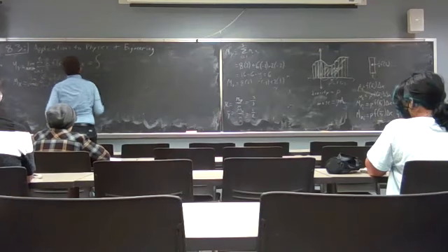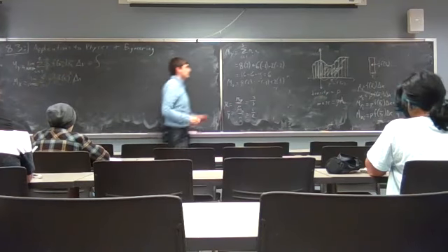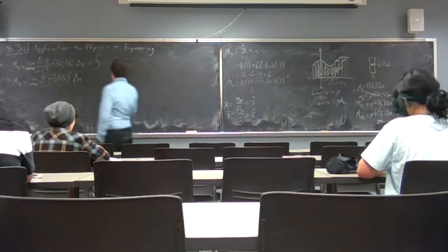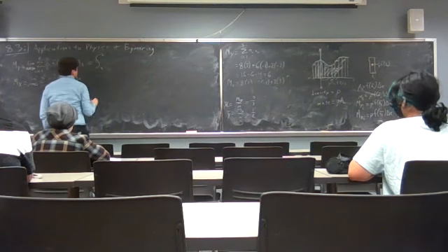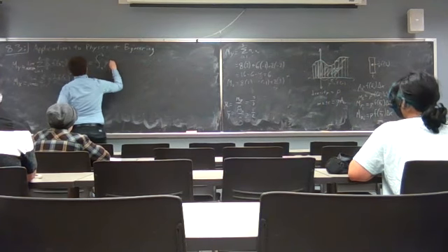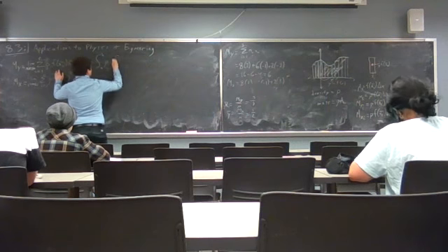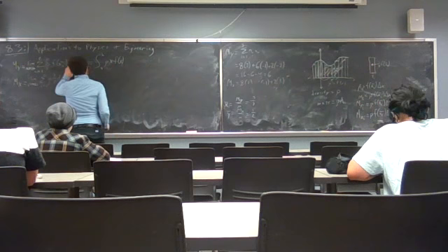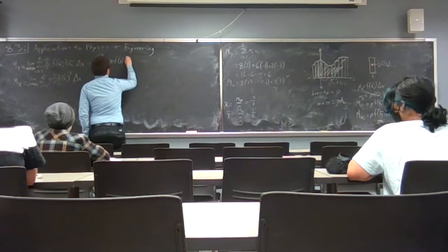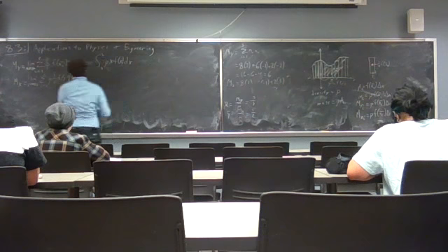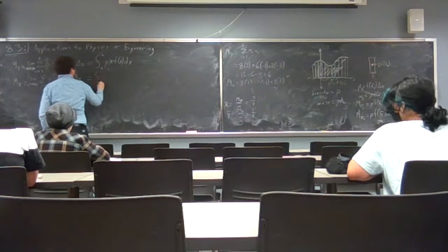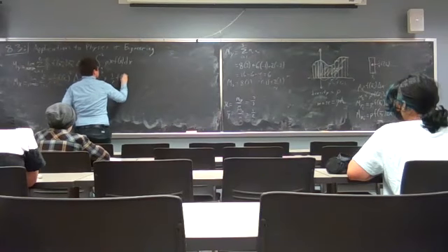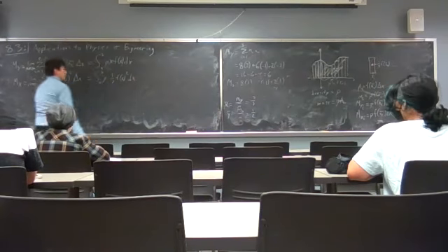So this is going to be the integral from a to b, since all of our rectangles are going from one end to the other here, of rho times f of x times x, replacing that xi bar, dx. And similarly here, we get the integral from a to b of rho times 1/2 f of x squared dx.